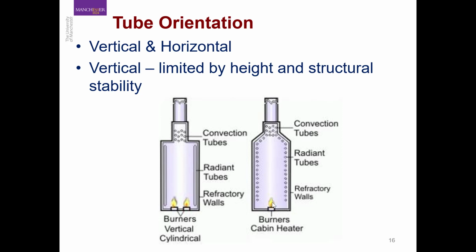Okay, and the reason why we use vertical tubes compared to horizontal tubes. As you can imagine, or you might have discussed in your heat transfer courses, when you have vertical tubes, you can use the gravity effect much more efficiently. For example, the water will be at the bottom, and if you are using a flame to make steam or heat, it will actually evaporate and move towards the top. Okay, so there is no clogging effect because of the fluid or the gravity of the fluid.